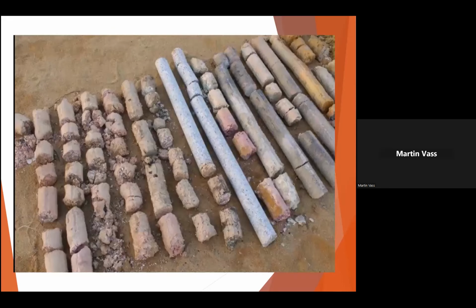The next slide I'm going to show you, if you remember the core drilling, this is what is extracted from the ground. And it's laid out in what we call a core box. So this material is laid out and allows the geotechnical engineer and the engineer to look at the material. Depending on how deep you're going to go, if you're going to do a lot of foundation work, a lot of basement work, then you may go fairly deep. If you're doing shallow foundations, it may not be that deep. Again, depends on what you find.